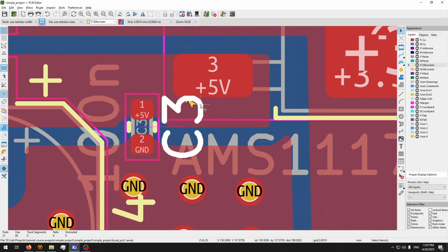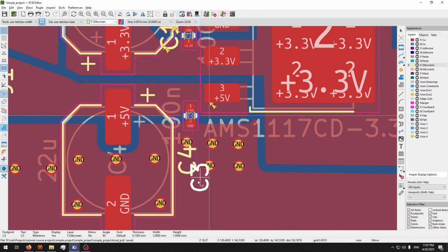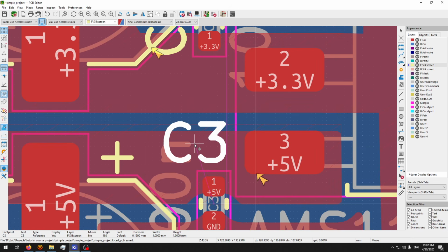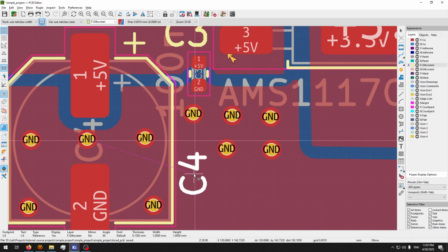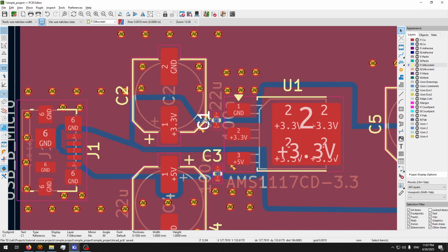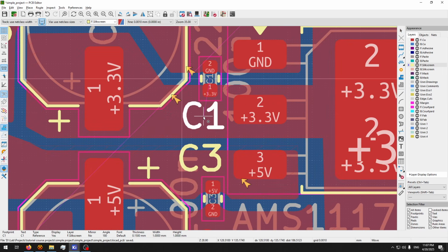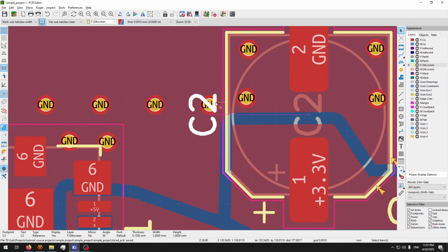Okay, let's go to the other side. See, this one is affecting the pad. This C3, which is this one, is affecting the pad. So I'm going to move it to here. This is C4, it's on the pad. I'm not going to lose anything by making it tighter, neater. This is C1, I'm going to make C1 similar to C3. This is C2. Look, that C2 is coming from the pad. The drill, when this is done, is going to drill through the number 2.